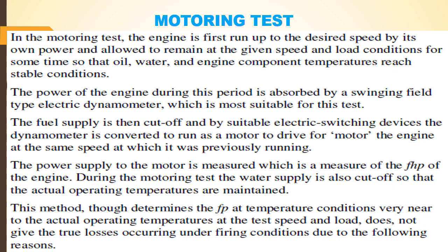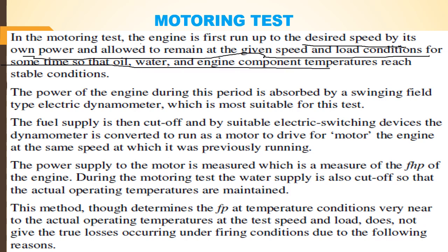Next is the motoring test. What we have to do in the motoring test is, the engine is first run to the desired speed by its own power and allowed to run at the given speed and load condition for some time, so that oil, water and engine component temperatures reach a stable condition. So this is a very important thing.